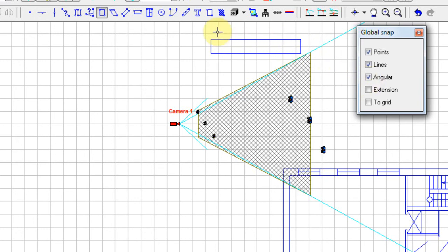An angular snap is used to draw lines, angles, cables, and also when moving and rotating. In this case, the subsequent points of the construction are aligned from the previous points horizontally and vertically. With the angular snap disabled, the direction of the line segment is not fixed. Extension. The cursor sticks to the virtual horizontal and vertical lines passing through the base points of objects. Snap extension is disabled in the Select Edit mode.